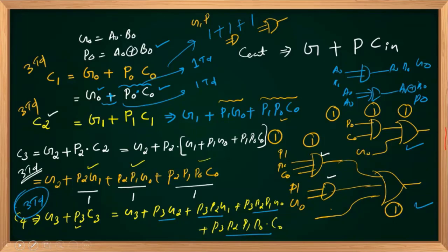Then we implemented individual carry outputs using separate circuits, separate logics, and that output is directly connected to the carry in of my respective adders. Of course, the second technique, the carry look ahead adder, will increase the hardware complexity, but the advantage is that the delay is reduced significantly. It's a constant, independent of the number of bits. Is that clear? Please respond.